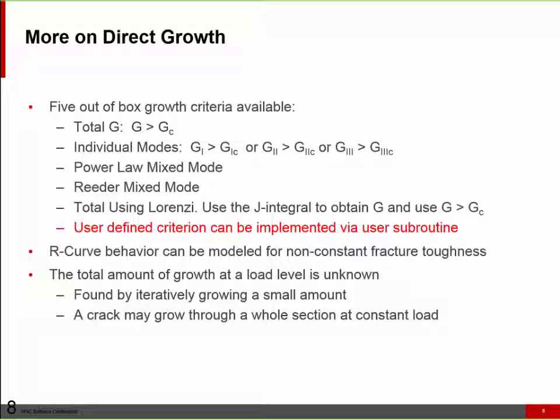In Marc, there are 5 out-of-box crack growth criteria. And the user can use user subroutines to implement his own criterion. The critical value in the criterion doesn't have to be a constant value, so that the R-curve behavior can also be modeled.